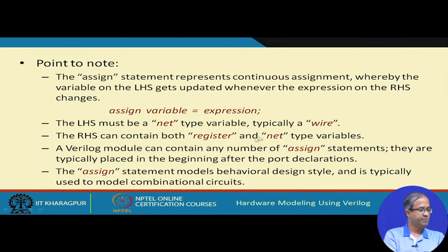So, after your port declarations and the temporary wires, you place these assign statements. And this is what I have said repeatedly, that assign models the behavioral design style and is typically used to model combinational circuits, but you can also model sequential circuits using assign. This we shall see later.